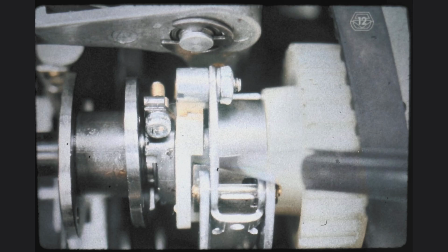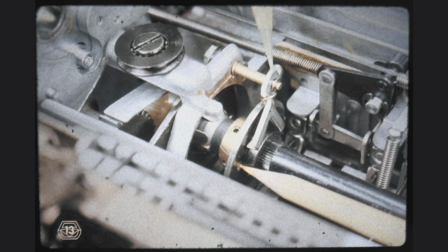Since it seems rather large in this picture, can you tell us how we check this clearance? Take a moment to decide on the correct answer. You are correct if you answered that we check the cycle clutch overthrow, or, for that matter, the whole printing mechanism overthrow clearance, by first rotating the cycle shaft until it finds its check pawl position. Only then can we check the overthrow play for the printing mechanism, and the play should be 1/4 of 1 millimeter.